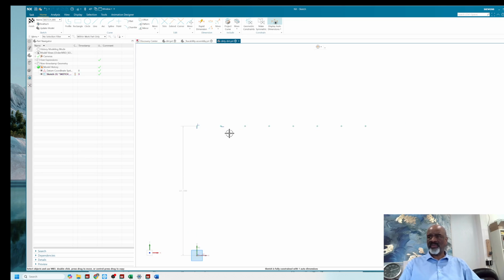All right, now I also want to be able to vary the height of each point. I've got the spacing, but right now I'm using the pattern command, so I can't vary each height. So I'm going to select this little indicator for the pattern and delete the pattern, and it's going to leave the points there. So that's really good.